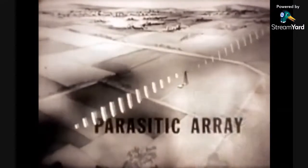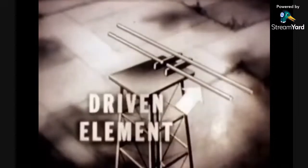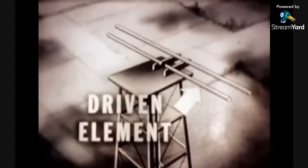But should your problem be to transmit energy in just one direction, an answer is the parasitic array antenna. In this array, the elements are aligned like those in the end-fire array. When two elements are used, the only element connected directly to the transmitter is called the driven element, which is a half wave in length. The second element is called a reflector and is longer than the first.